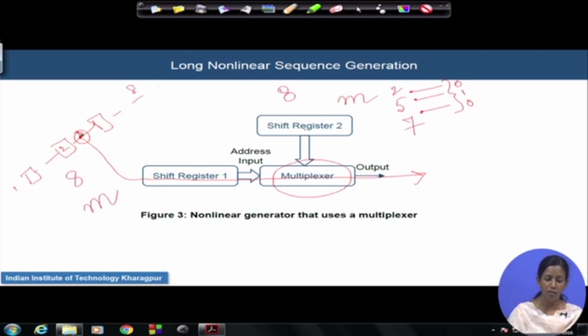The instantaneous value that is generated is taken out as a code bit. If I now observe over a pulse of say 10 or 15, I will get a series of bits coming from the different stage outputs of the shift register, and that is my generated code.